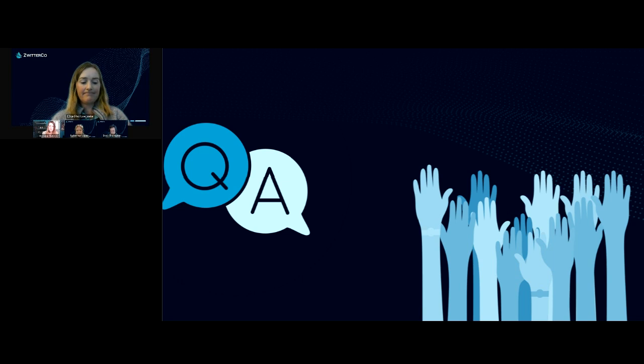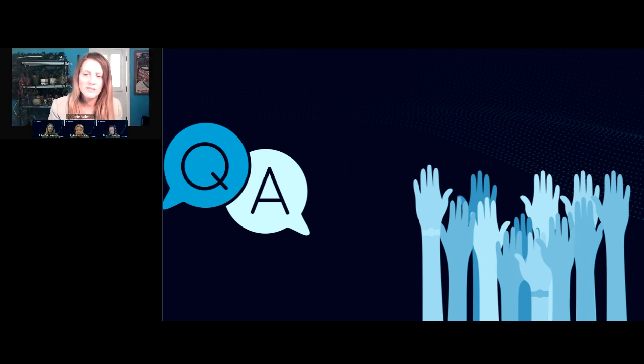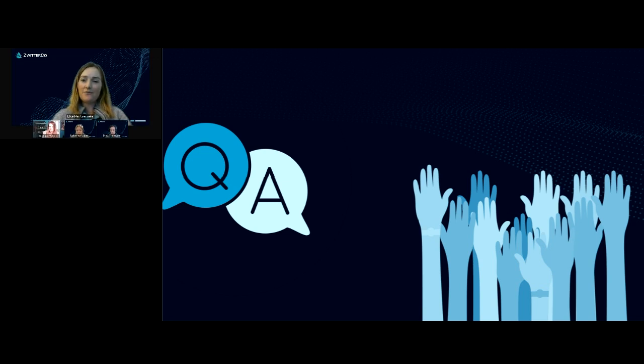And here's another question about chemicals. Can ZwitterCo membranes be resistant to free chlorine? Yeah, our Zwitterionic technology itself is resistant to chlorine, but when it comes to the RO product, we have the Zwitterionic technology integrated with the polyamide RO membrane. So the polyamide is really the limiting factor. So no chlorine for the RO products, which is very similar to conventional RO elements that are available today.